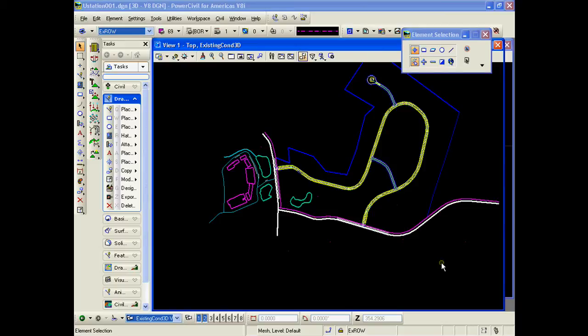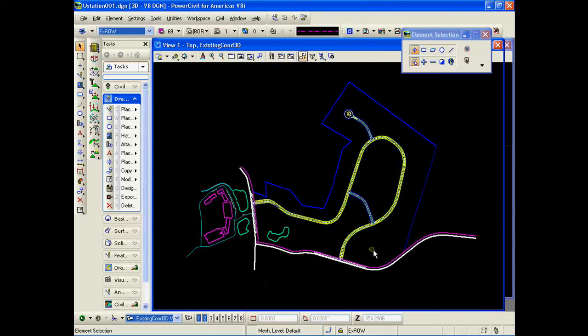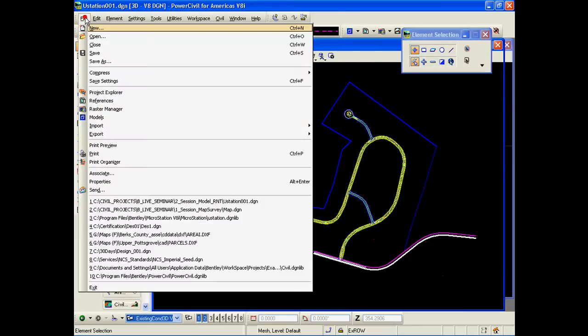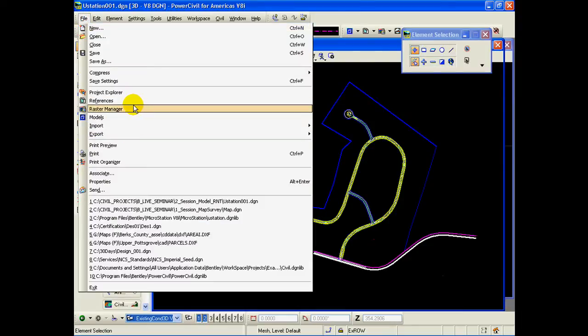Okay, what we're going to do is create an elevational drape for some imagery. The imagery we're going to be working with to start is a SID file. Now, a SID file we're not able to create a drape material from, so we're going to have to convert the SID to a format such as PNG or TIFF or JPEG that we can work with. If our imagery is already in that format and georeferenced, we can pick up the process accordingly.